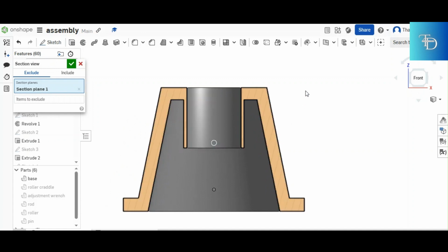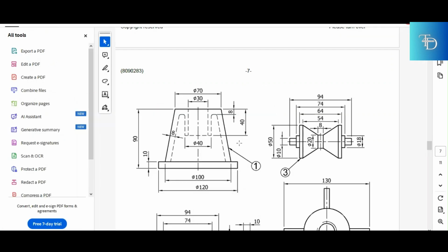Usually every time you section something, let's look at the front view again. Usually you see there are hidden details that are flowing inside the part on the outside view. But now if this thing is cut in half, those hidden details get exposed. You get to see what's on the inside, because they were being covered by the outer surface of the front view. That's why you were not able to see the inside of the part, hence the hidden details.